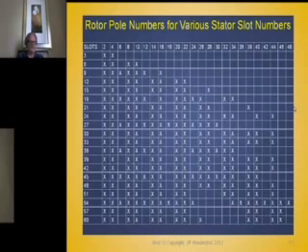A 2-pole machine will work with every possible number of slots. But one of the most difficult ones is the 6-pole motor, which has a minimum number of slot combinations that will give you balanced windings. And then, of course, multiples of 6, the 12, 18 and 24, all have the same difficulty of having enough options. The reason that other combinations don't work is because you can't get identical sets of phase windings distributed around the stator 120 electrical degrees apart. That's why you don't have X's in some of those other combinations. It's basic number theory. It just doesn't work out.